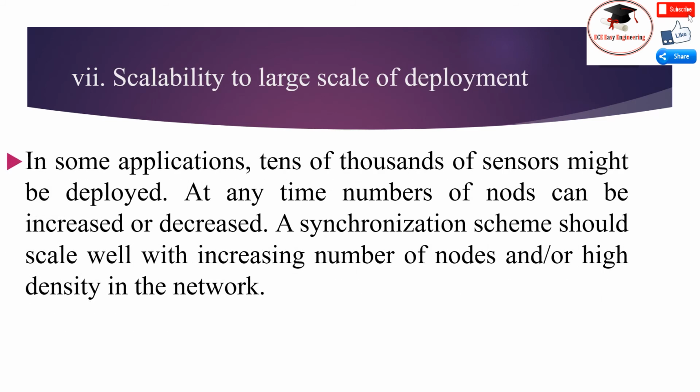The seventh challenge is the scalability to large scale of deployment. In some applications, tens of thousands of sensors might be deployed together. At any time, the number of nodes can be increased or decreased. A synchronization scheme should scale well with an increasing number of nodes and a high density in the network.